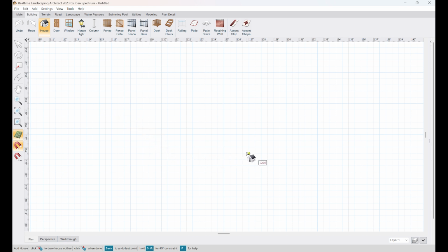You can see how it moves. It just moves per grid increment, which is good because it keeps things locked into straight lines and works in a grid without having to freehand draw anything. If you turn off the magnet, then you can see how it flows and just follows your cursor here. So for at least the time being, I think it's best to start with the magnet on, and that way you lock into the grid for clean movements.